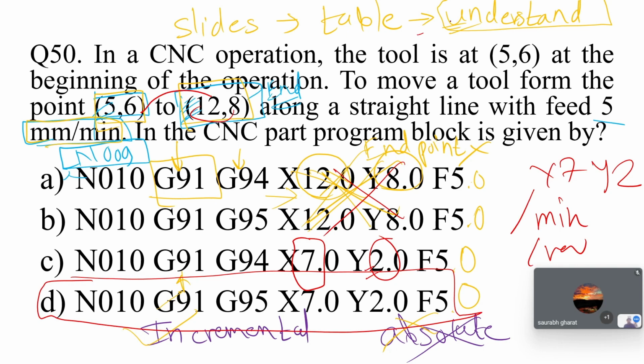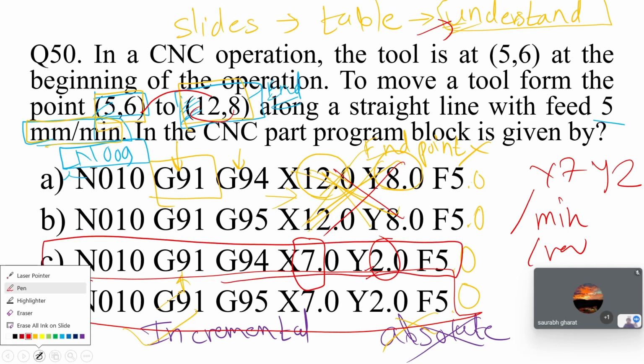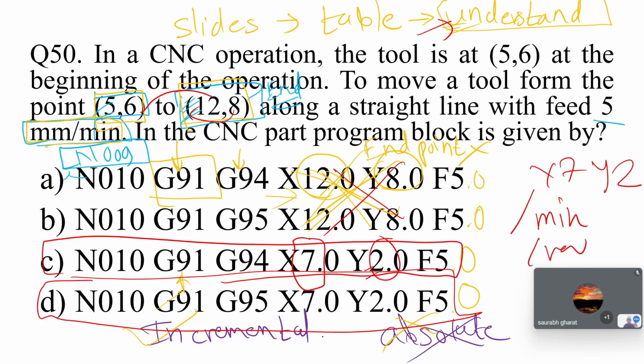Go through the tables, understand each and every part, and after that apply the code. Or you can use the simulator also. If it is going too fast, it is problematic. These parts are also important while you are coding. G94 is the only correct option here. If you go G95, it will damage your machine. You can't use it.